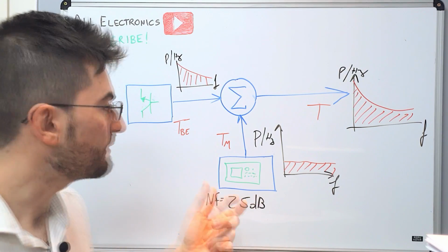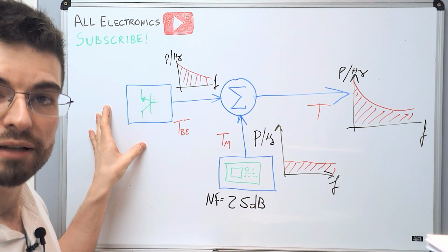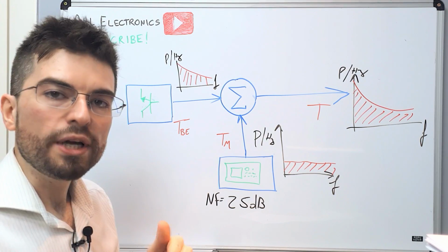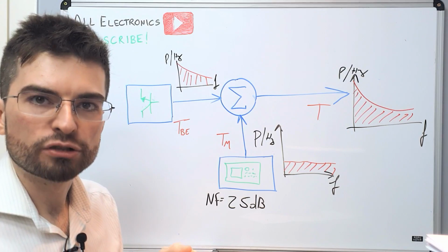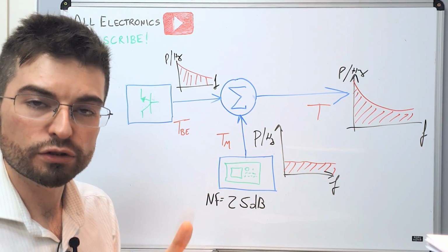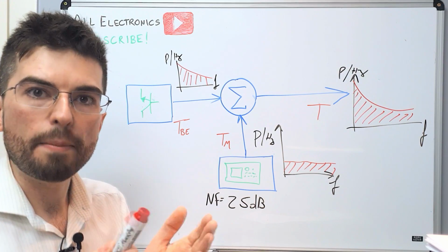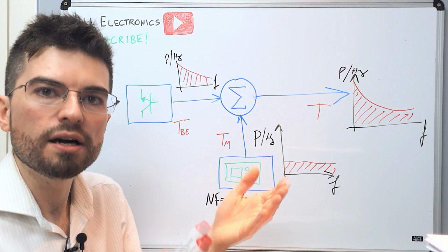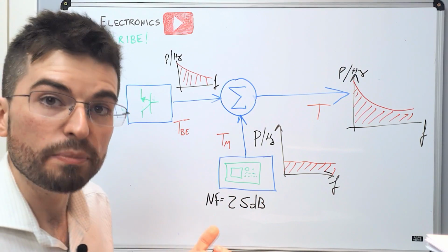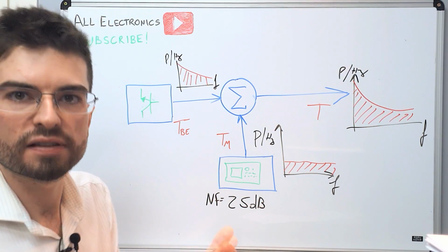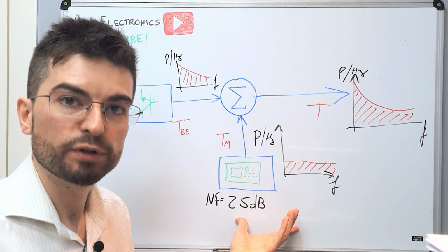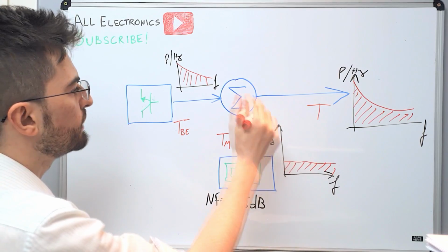After that, we characterize our device, doing again an automated measurement. We can transform both measurements to noise temperatures, just converting the dBm per hertz noise density to a noise temperature with respect to a 1 hertz bandwidth, and we can subtract both to compensate for the noise floor of the spectrum analyzer.